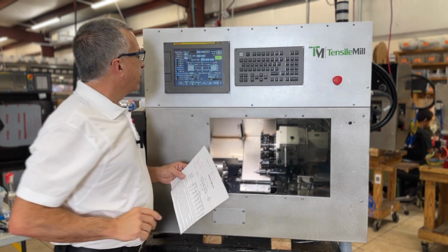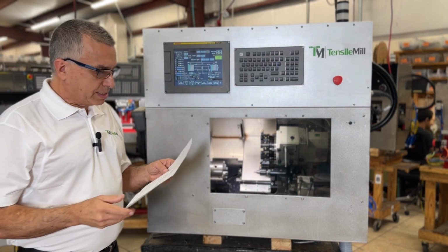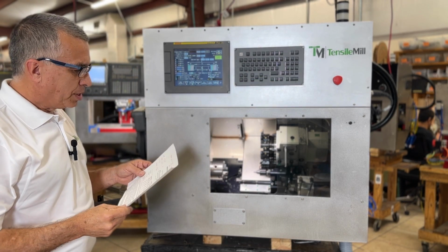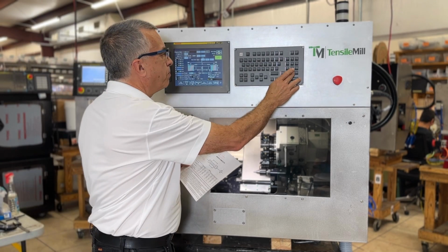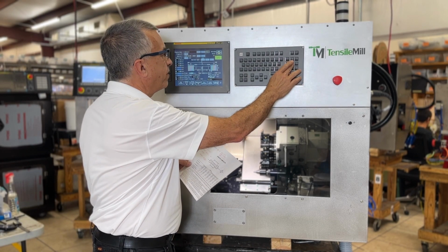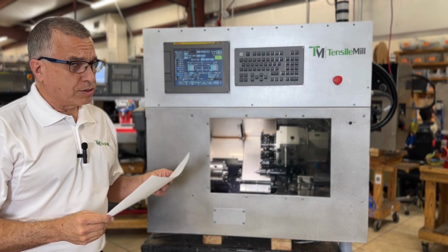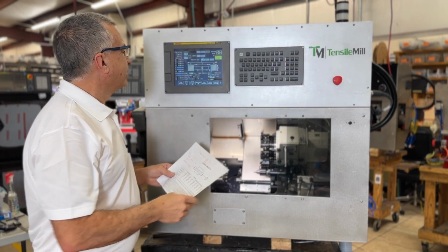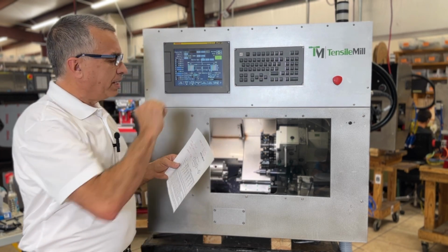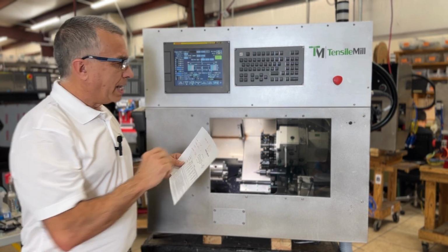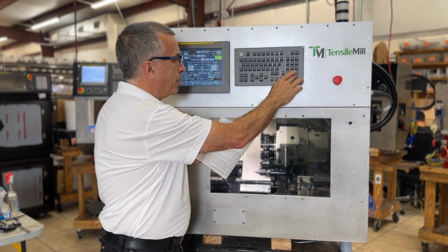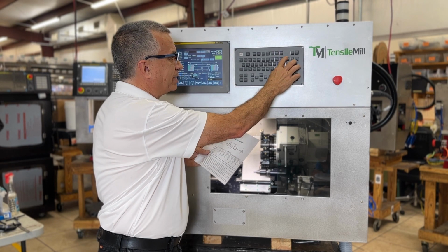And then I go with the thread. The thread, I need to specify the pitch. The pitch of the thread is 0.0556, which is actually 1 divided by 18. And the height of the thread. The height of the thread is 0.0417.